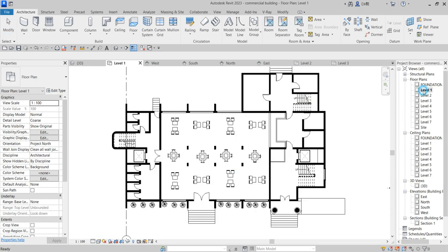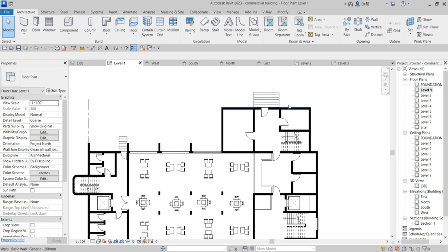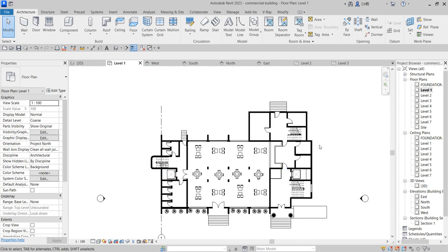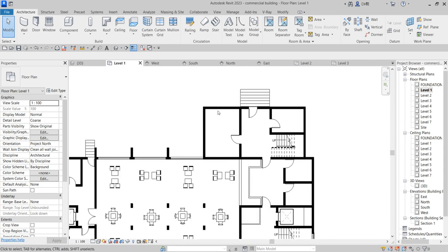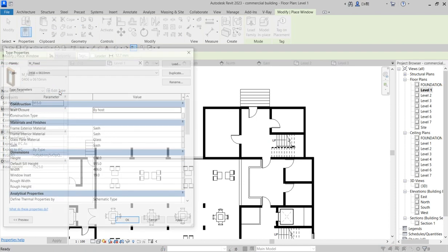But before then, let us go to the floor plan and put what it needed to be, the last set of openings to hold this space, and put the right graphics in order before we later do the working drawing, probably a few other mechanical and structural activities that are needed. So now what we do here is that we want to place the windows into this place. So click on the window component. So the type of window we want is just a long one, so you can use this particular one, just say edit type.